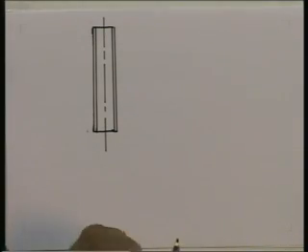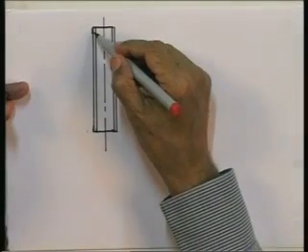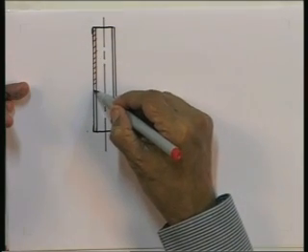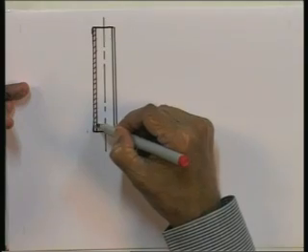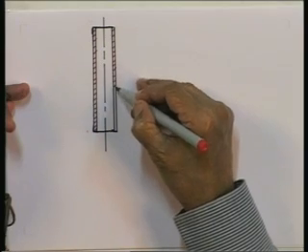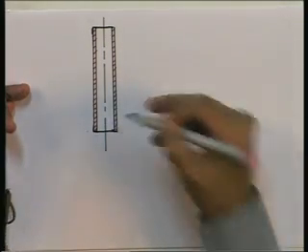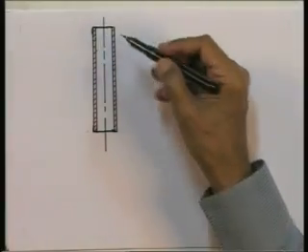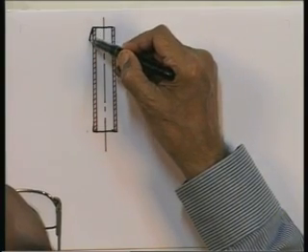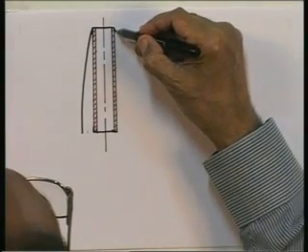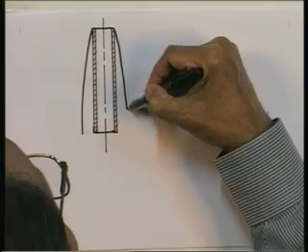Let us say this is the vertical tube and this is the wall of the tube. Condensation is taking place on the outside. I will draw the film thickness exaggerated again. So, this is the condensation taking place on the outside with the film thickness of course exaggerated all round the tube. So, it is like condensation on a vertical plate.